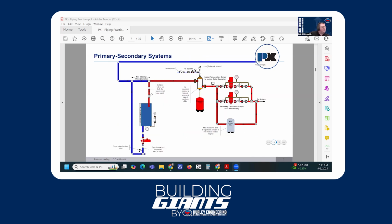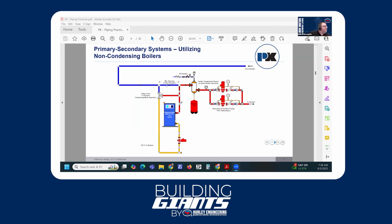Okay, so I wanted to move back. We kind of left off here yesterday talking about primary-secondary, but I wanted to talk about how that relates to systems that we're going to start seeing more and more of, hybrid systems that might use a combination of different technologies like heat pumps and condensing boilers, or potentially condensing boilers and non-condensing boilers. Before we get there, let's talk about a non-condensing application.